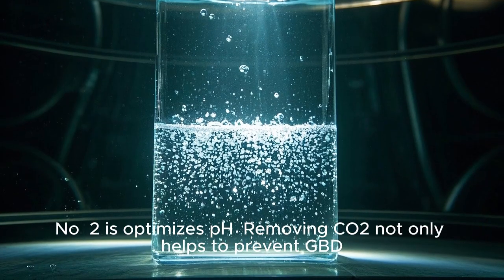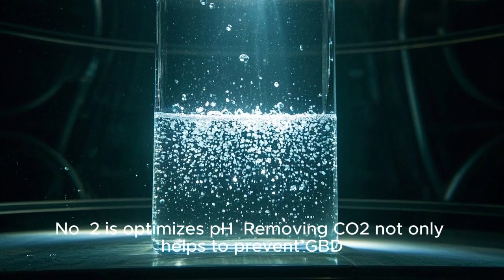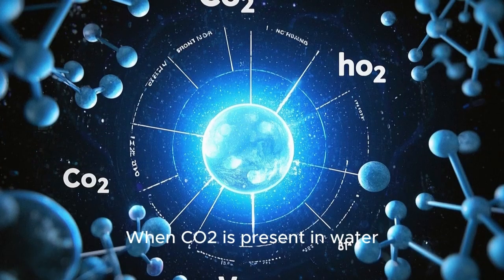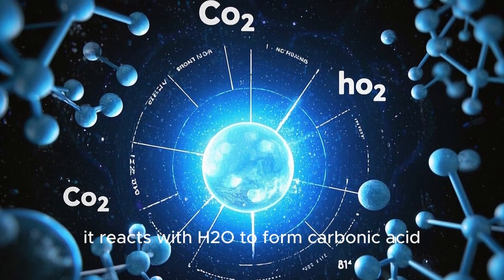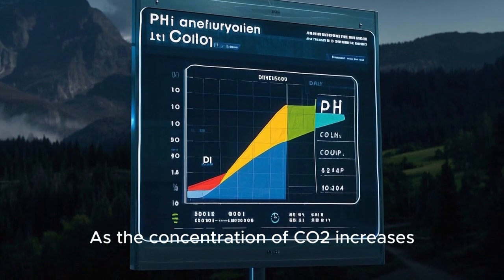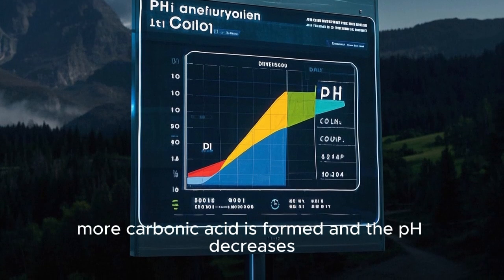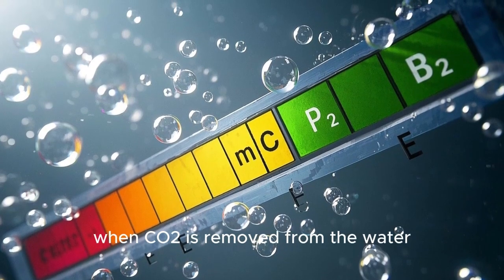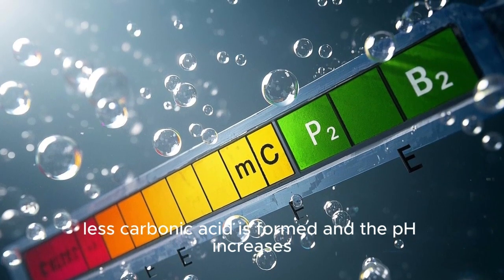Number 2 is optimizes pH. Removing CO2 not only helps to prevent GBD, it also helps optimize pH. When CO2 is present in water, it reacts with H2O to form carbonic acid. As the concentration of CO2 increases, more carbonic acid is formed and the pH decreases. Conversely, when CO2 is removed from the water, less carbonic acid is formed and the pH increases.